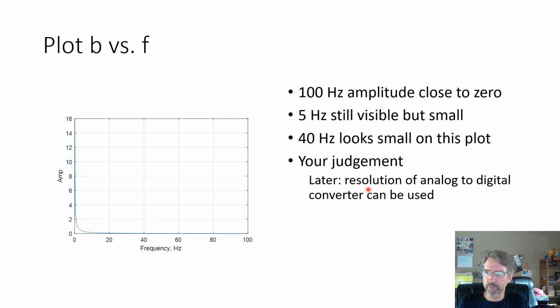So if it's 0 to the precision of the analog to digital converter, then it's 0 for all practical purposes. So where this goes through 0 to the resolution of our measurement system is another approach, and we'll use that later in this class. So that should give you an idea of how to do the Fourier series and how to use the Fourier series to find FM for the sampling theorem.